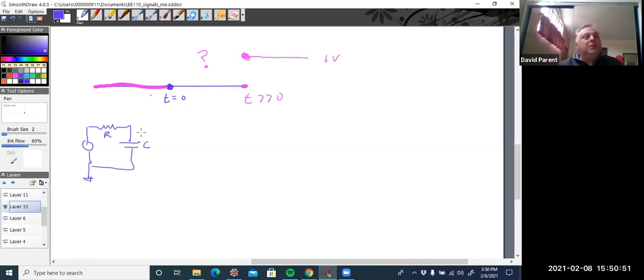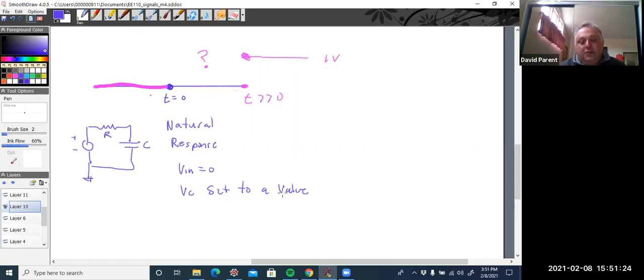The time domain can be a little more difficult when using differential equations. So what sometimes can be the better thing to do is find the natural response, which is V equals 0, VC is set to a value, and see what happens.